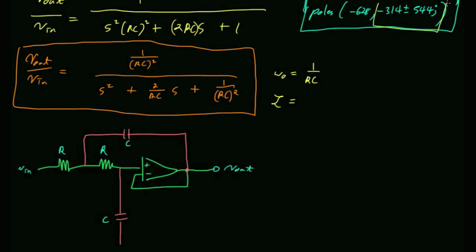Omega naught is negative 314. Close. No. Make it into polar form. What's that going to do for me? Then the left side will be omega. Oh, yeah. We learned that, right? Do you remember how we learned that when you have complex poles and you convert it to polar form, what you're left with is omega naught e to the j theta, right? And then the theta was basically set by the damping ratio, by zeta. Yeah, absolutely.